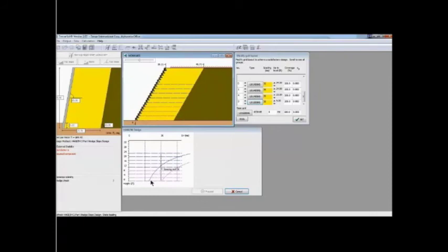But with UX 1400, we would have to be somewhere around perhaps 22, 23 inches in order to be a passing design and have the spacing okay. So this is all about the spacing of the geogrids, not about the strengths at this point in this software. So we need to make sure that the spacing is okay, that all these points fall to the left of the curve line for that strength geogrid. And we can do that by adding geogrid up to the top.